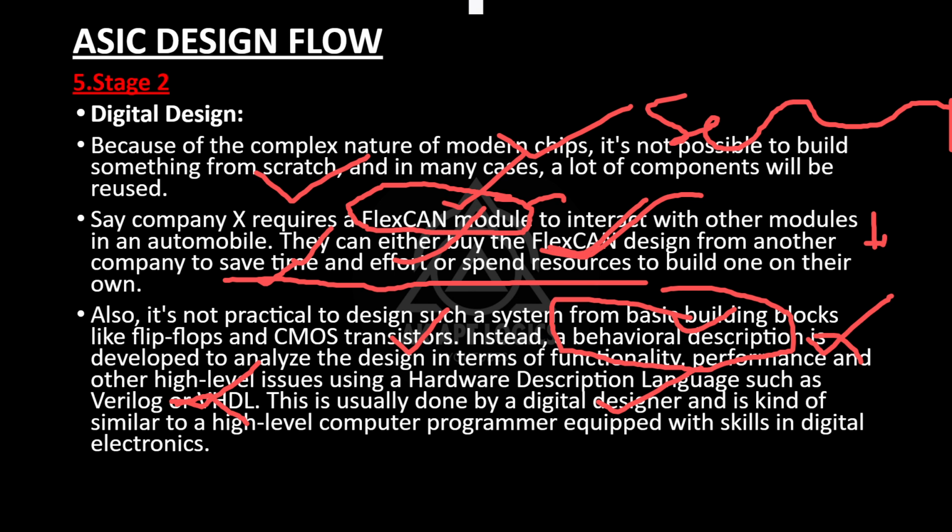Optimization is very difficult using the behavioral model, but writing the functionality of the code in Verilog or VHDL is very easy compared to the RTL and gate level model, because using the behavioral model we just need the higher level details of things. It means if we just know the functionality of the design, then we can do the behavioral code.